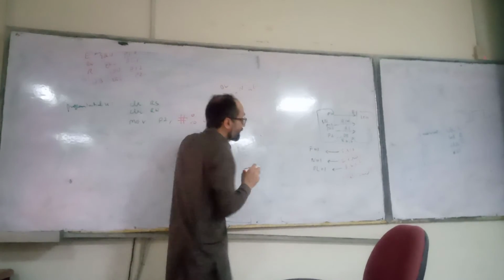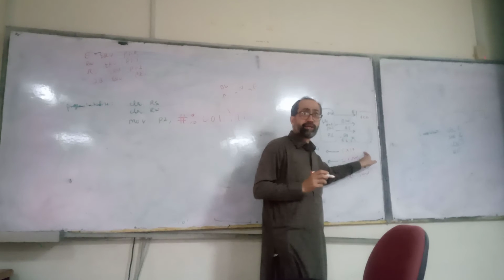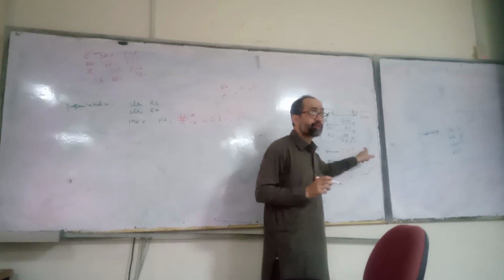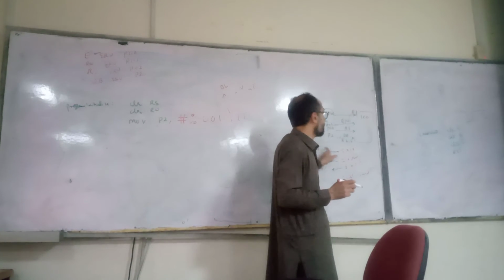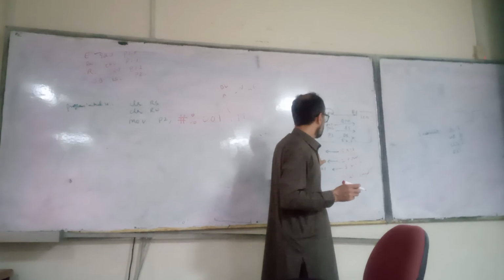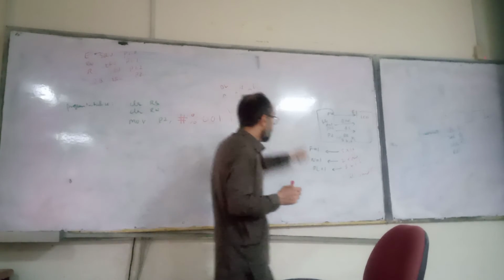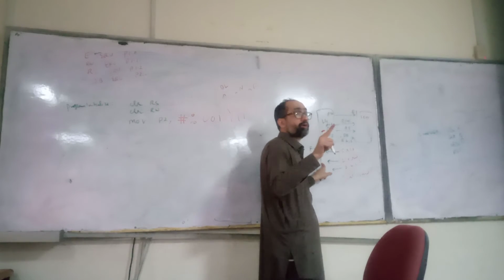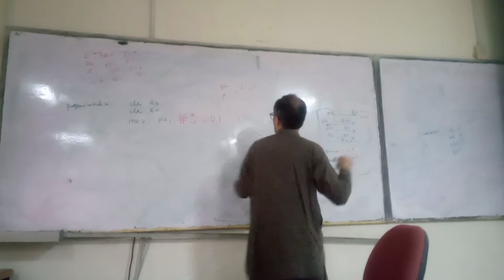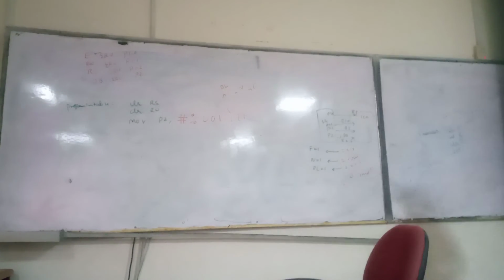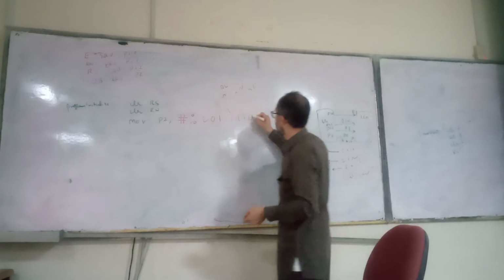Why should DL be 1? Because we want to configure it into 8-bit mode. And for the 5 cross 7 standard display, F will be 0. If you want to configure it into 1-row mode, N will be 0. In the last, the last 2 digits are don't care, so you can make it a logical 1 or logical 0, it doesn't matter.